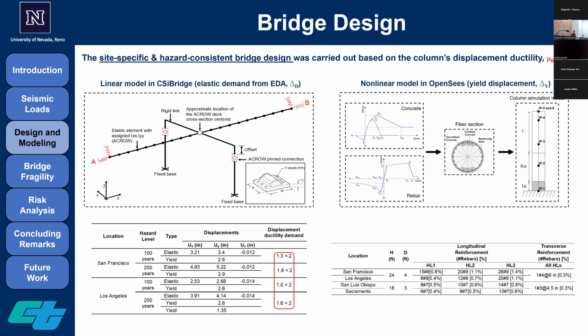And for the sake of this research, since they are temporary bridges, we are not expecting to see super ductile behavior such as the ordinary bridges that provide essential connection. That's why we are checking a ratio below 2, which can guarantee the expected behavior corresponding to the temporary bridge that we use.